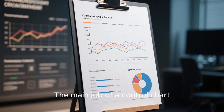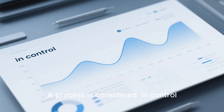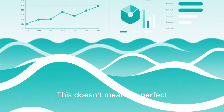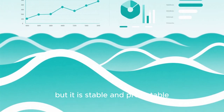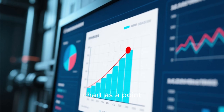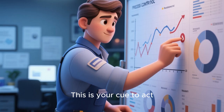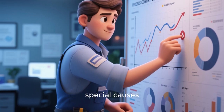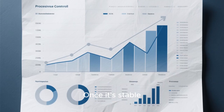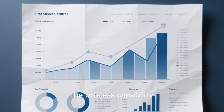The main job of a control chart is to help you distinguish between these two types of variation. A process is considered in control when only common cause variation is present. This doesn't mean it's perfect, but it is stable and predictable. When a special cause occurs, it shows up on the control chart as a point outside the control limits or as a non-random pattern. This is your cue to act. By identifying and eliminating special causes, you bring your process back into a state of statistical control. Once it's stable, you can then work on reducing the common cause variation to improve the process capability.